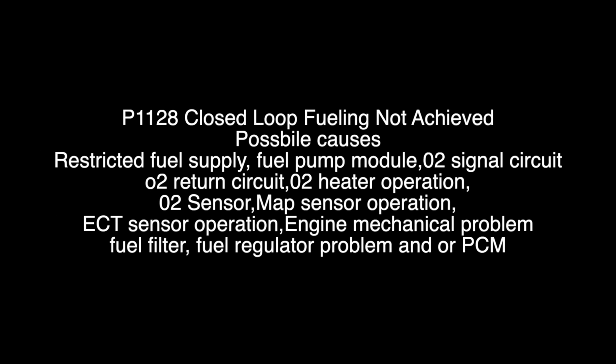Now with the P1128, closed loop fueling not achieved, the possible causes are, but not limited to: restricted fuel supply, fuel pump module, O2 signal circuit, O2 return circuit, O2 heater operation, O2 sensor, MAP sensor operation, ECT sensor operation, engine mechanical problem, fuel filter, fuel regulator problem, and our PCM.